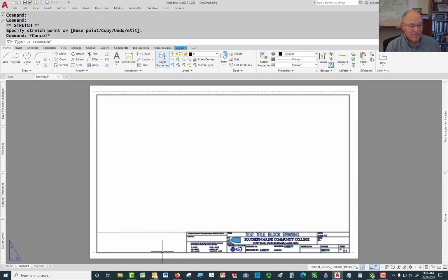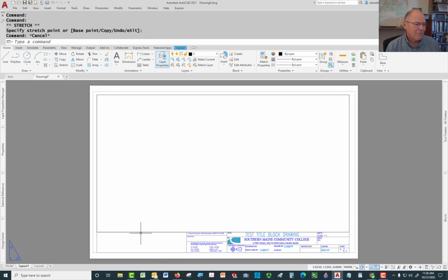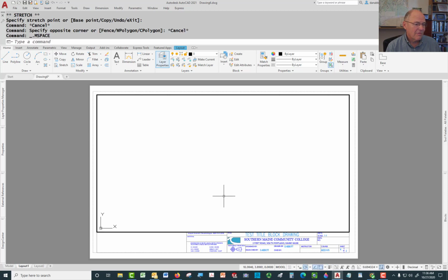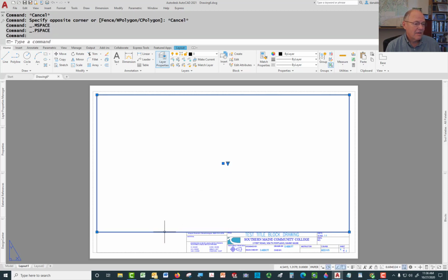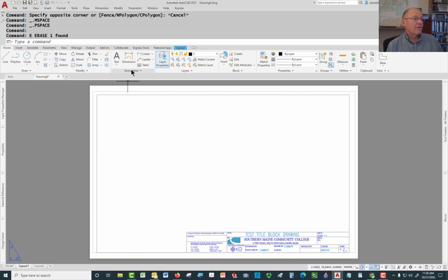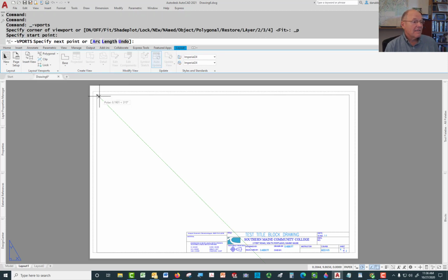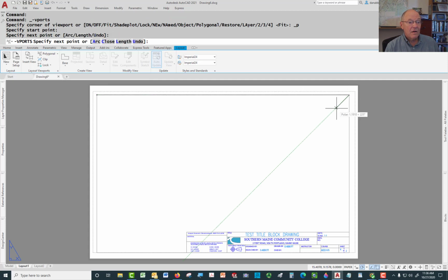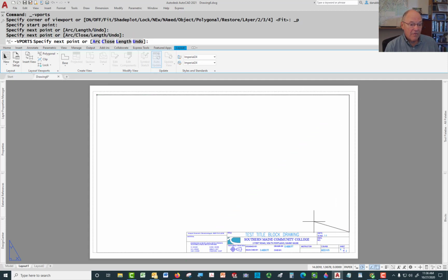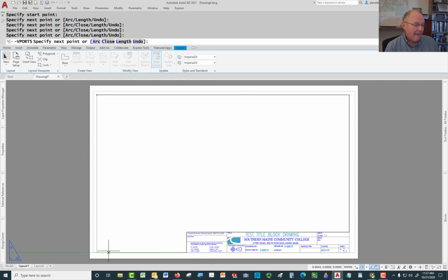But you could make a viewport. Right now my viewport's rectangular. I could make a viewport if I go to the Layout tab, and the Layout tab up here, if you take a look, is that one. If I go to the Layout tab and I say I want to do a polygonal layout, I can say do a viewport that completely fills the area that you could draw.